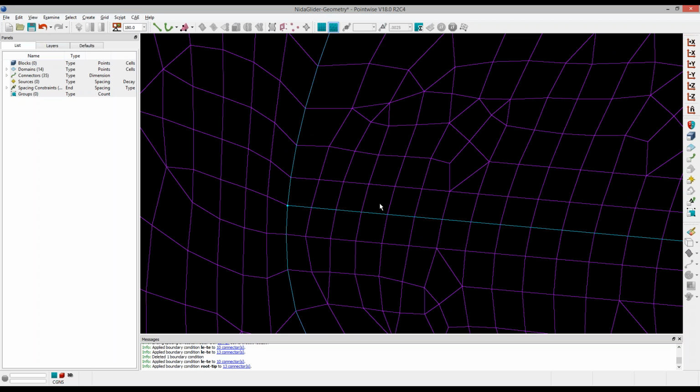If I didn't do that, I would have some anisotropic stretching in the spanwise direction directly adjacent to these smaller quads, increasing my area ratio. And here we come back to talking about area ratio, and we're actually going to examine that once we're done with the surface mesh. But the idea is if you keep your area ratios low, when you generate that volume mesh, you're going to have a really high quality volume mesh in these vicinities.